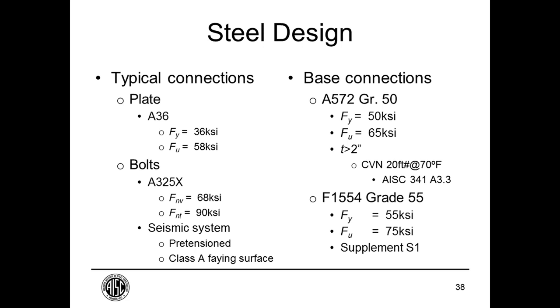Now, the reason we have a threshold of 2 inches has to do with observed material toughness from multiple tests. The thinner material tends to have high toughness, and low toughness material seems only to crop up for these thicker elements. So we only ask for the testing for the thicker elements because we're pretty confident we'll get that toughness without spending effort on testing for the thinner elements.